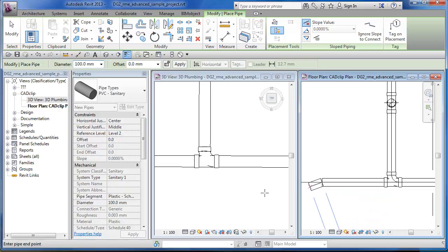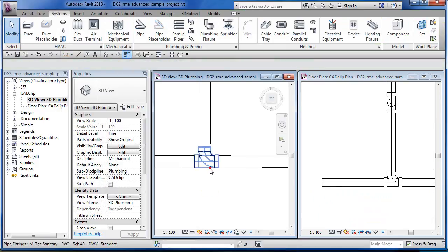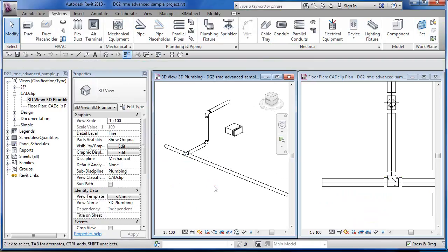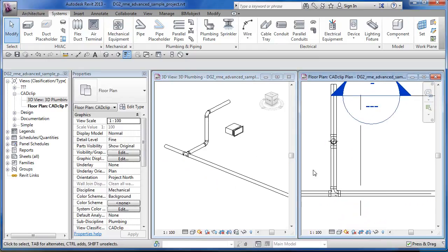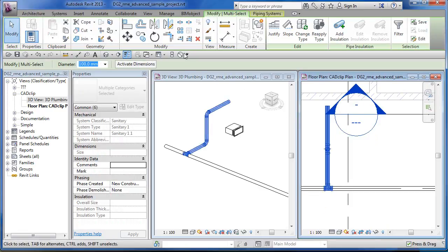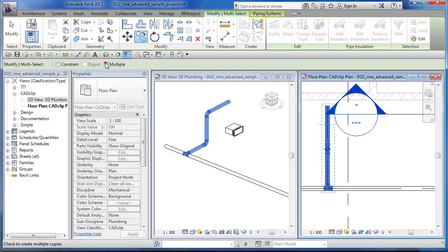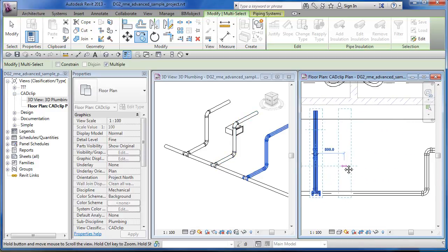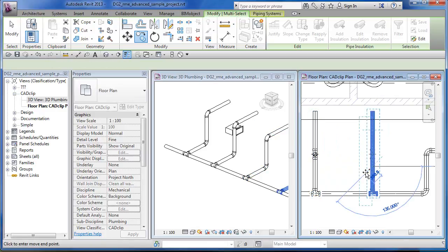And then we can draw another segment in there, hit escape, escape, pick over here, pick on this object, shift middle mouse so you hover around that object, zoom out a little bit. Now maybe just to speed things up, we'll say, well, why don't we just copy this along? What would happen if we did a window like this, and then just went copy and said multiple, and then went here, and you can type in a number like 1300, and it'll go that 1300 units away. Because we said multiple, we can go 1500, type in any number, add one more in, then hit escape, escape, click out.